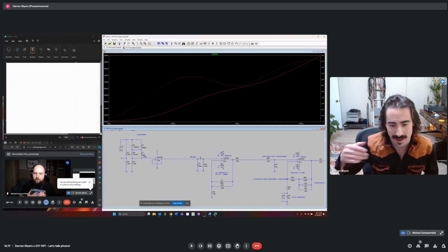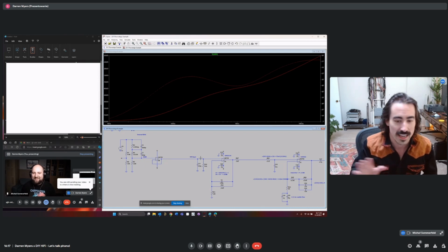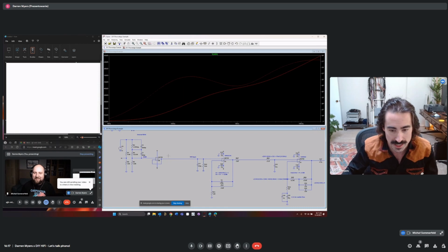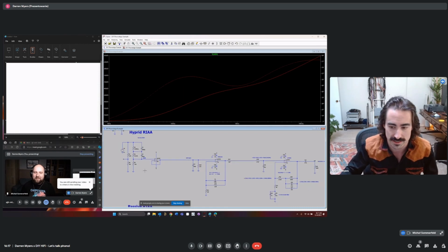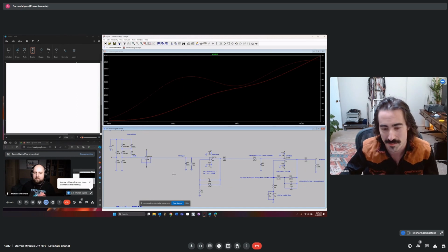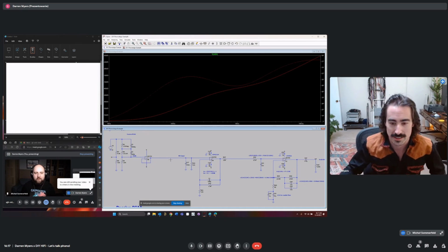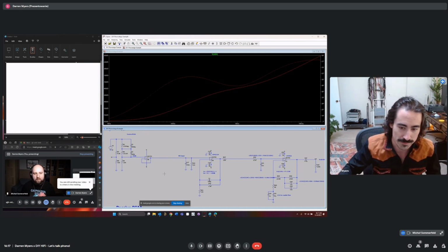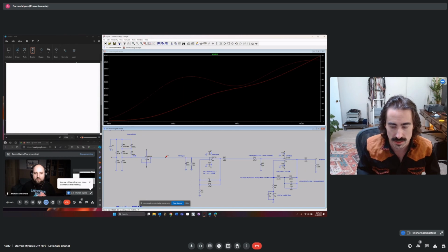Then I've spent 3 hours trying to figure out why something doesn't make sense, and it's really because I didn't isolate it. So I always isolate my impedances in LTspice and sim programs, just so that I don't make that mistake. But that's why that's there. So this is just trying to give us an accurate test signal, so that we can test the performance of our phono stage.